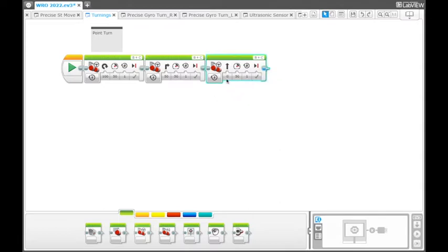The curve turn is like all the values except the point turn values, which are 100 and minus 100, and the single motor turn values, which are 50 and minus 50, and 0. If you use 0, then it will go straight. So except 0, 50, minus 50, 100 and minus 100, whatever value you put in the steering value parameter, you will be performing a curve turn. Based on your requirement, you can adjust the steering value and use the curve turn for your challenge. So this was using move steering.